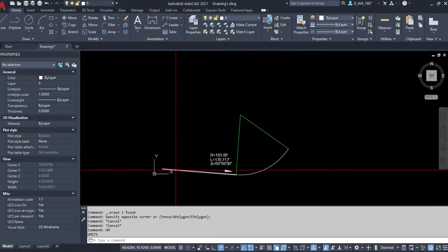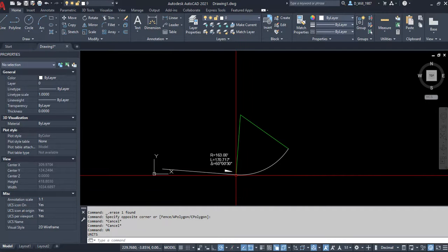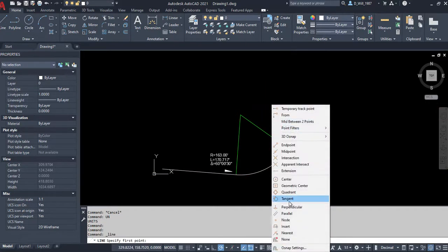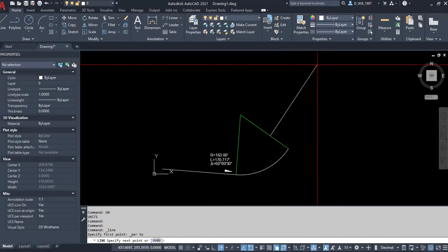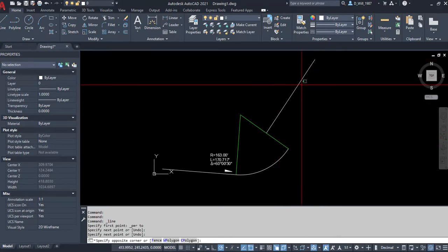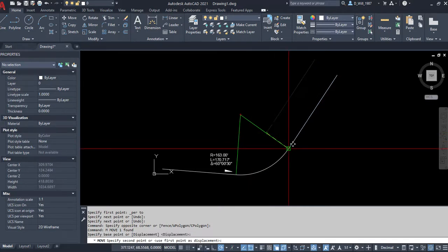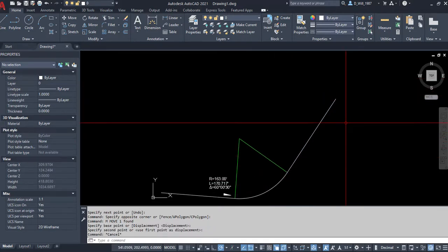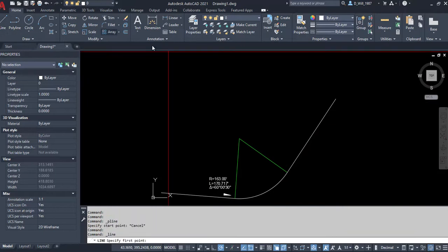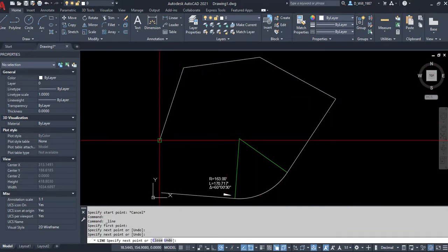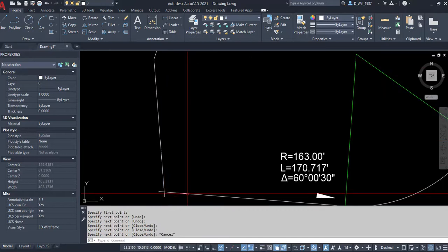Alright, so if that's your start point, do your segment, do your arc. I'm imagining your next arc will be tangent to that, your next line will be tangent to that arc, for whatever length it is. And when I'm drawing parcels, the understanding is given distances and bearings, you're going to get this at the end.